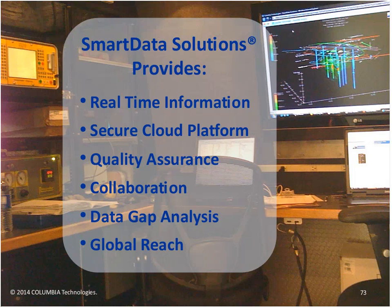But essentially what we're taking is information from the field, moving it to the desktop on a GIS-based system in a secure cloud platform. So as that boring, like many of the examples we've looked at so far this afternoon, is created in the field, it is then displayed on the information system, and you have an interactive platform that allows you to look through that vertical depth spectrum, build your own transects that we've been talking about, compare one boring to another boring in terms of relative response, and look at that in relationship to the existing monitoring well or sampling data.